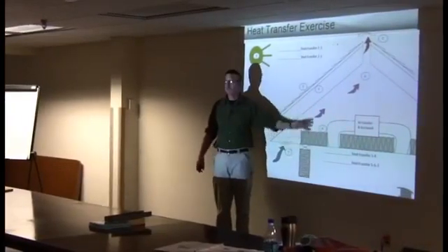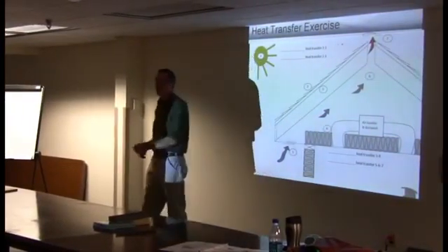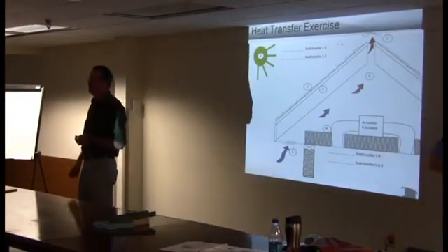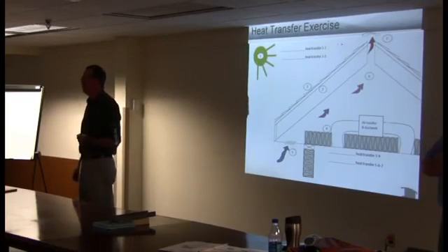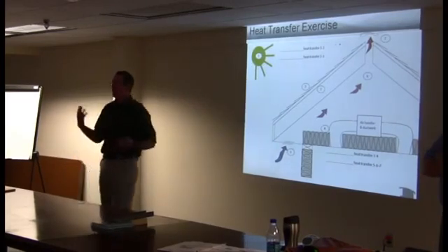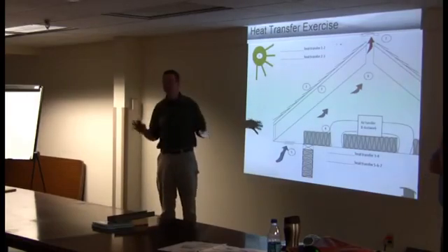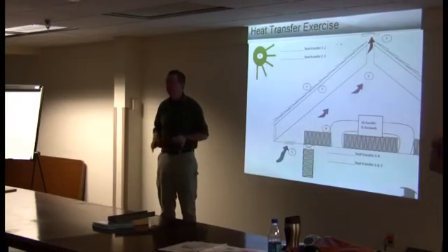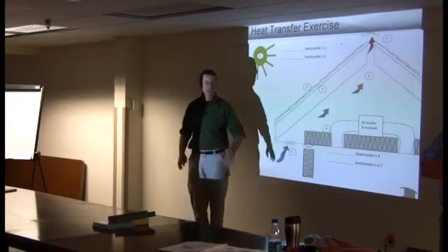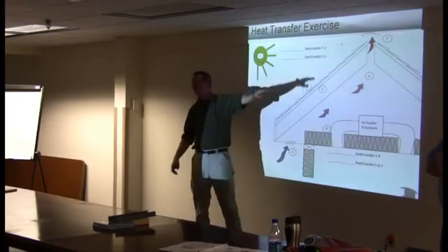But when you vent a roof or vent anything and you live in Georgia, what are you actually letting in when you vent? You're letting a lot of humidity in, right? Yeah, a lot of moisture. So that's a concern. I think for commercial buildings, we really would be better served generally to not vent and to just run insulation along the roof line.